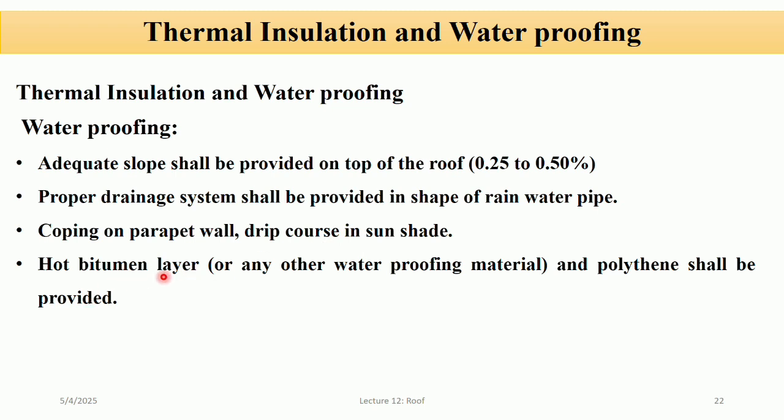And a hard bitumen layer. A layer of hard bitumen, a waterproof black substance, is applied on the roof as a sealant. It creates a watertight barrier under tiles or concrete screeds. An alternative includes modern waterproofing material like membrane, liquid coating, or polythene sheet. Polythene sheet acts as an extra barrier to stop water from reaching the concrete slab.